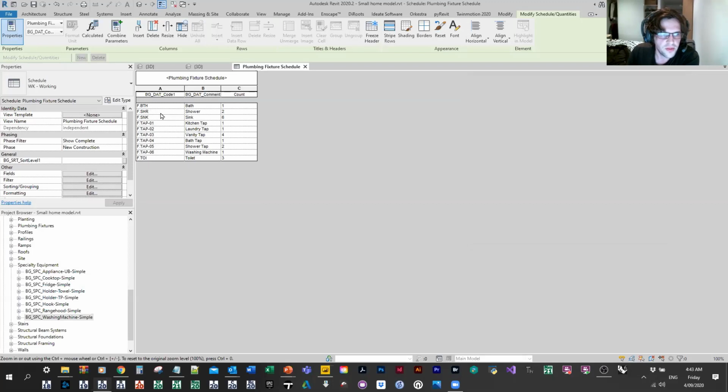So we can see now that I've got like 2 showers, 6 sinks, 1 tap, it's all getting clumped together, and count by default is a special parameter in that it knows how to total itself without you having to tell it to form a total. But there are other parameters that work a little bit differently.